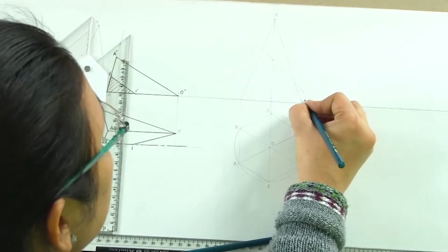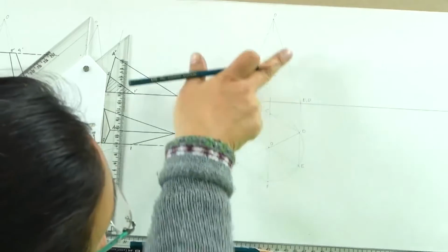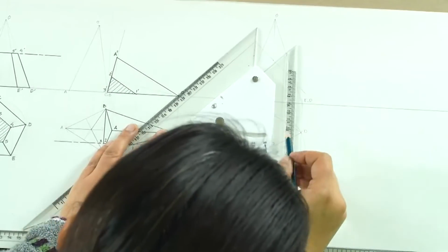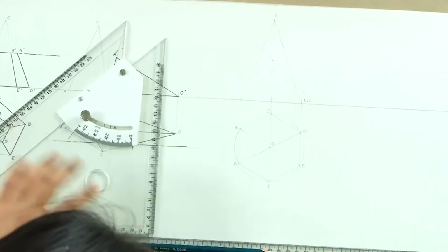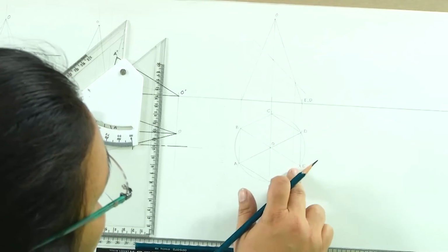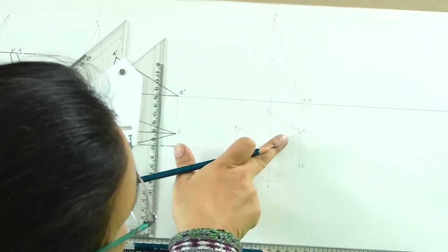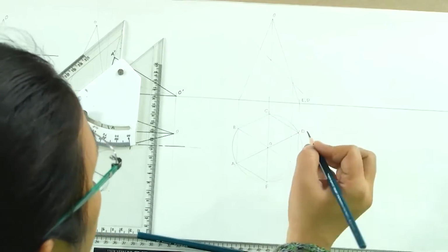This edge is actually both OE and OD. So, where are OE and OD being cut? It is being cut by the plane at this point. So, when I project it back onto the top view, these are the 2 points where OD and OE are being cut respectively. So, I get these 2 points here.